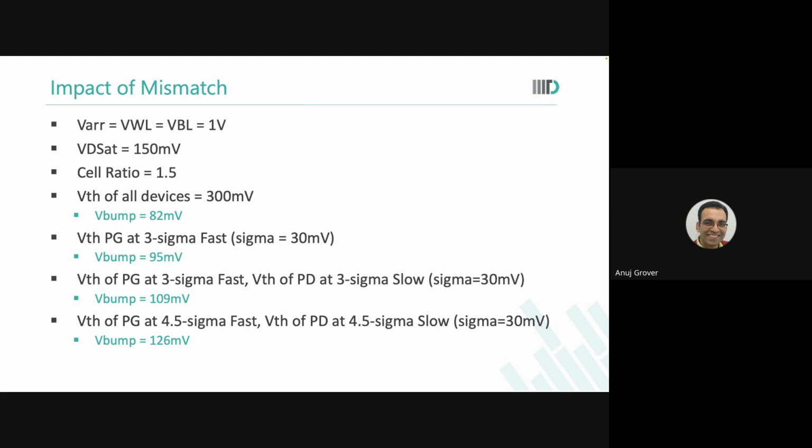So in totality, I would need to cover 12 sigma, 6 sigma on this side, 6 sigma on that side. But on the worst side, I will go only 6 sigma. That's sufficient. Otherwise, I will not be able to design anything at all. Already at 6 sigma I am worse than the nominal of cell ratio 1. If I go to 12 sigma, where will I be? So that 12 sigma accounts for both the positive lobe and the negative lobe.